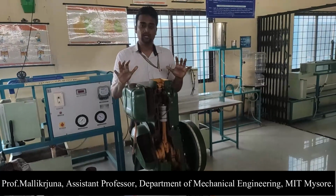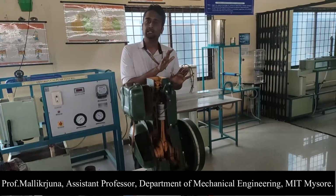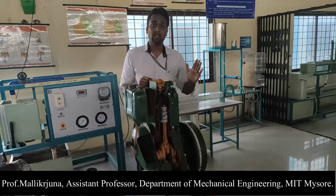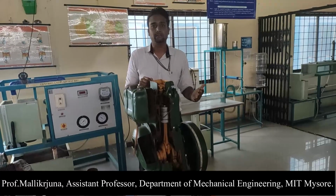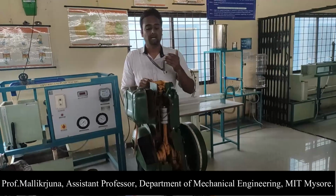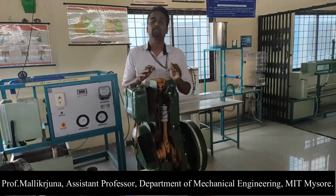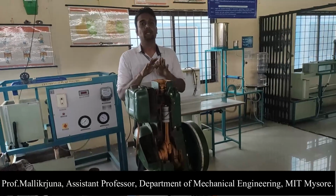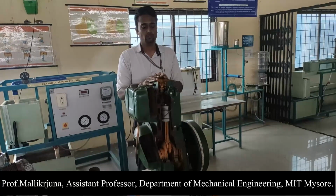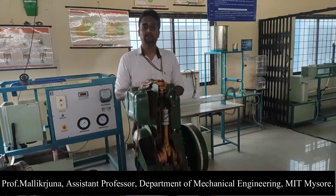So the readings are very clear now. Inlet valve opens before the piston reaches TDC. Exhaust valve closes after TDC. Inlet valve closes after BDC, and exhaust valve opens before BDC. So these are the various readings that I have to look at. This is the values that I have to take from the experiment.